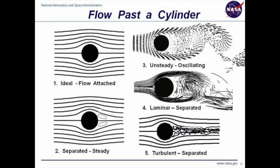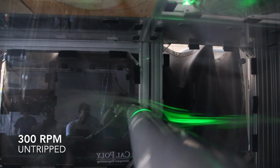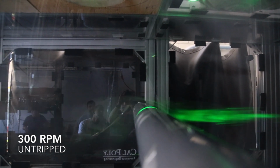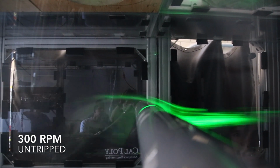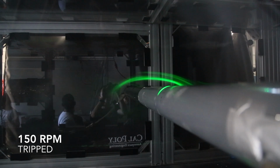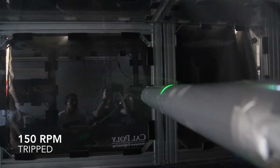As the flow separates from the cylinder, it will often create an oscillating flow known as vortex shedding. This effect is best seen in the video of the flow because as the tunnel speed increases, it is clear to see that the vortex shedding effect decreases. In a similar manner, by adding surface roughness to the cylinder via trip strips, the flow stayed connected longer.